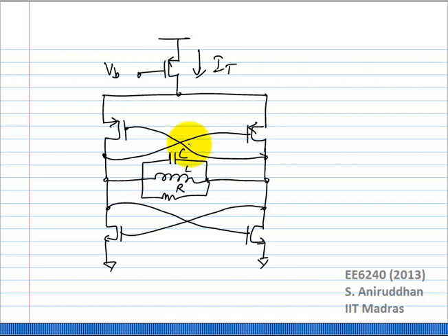Okay, so let us take the first example. So he said that for the same current I get twice the negative resistance. Correct? So let us say this was GMN, and I make sure that GMP equals GMN. Suppose I had taken the original NMOS cross-coupled oscillator and just made the width 4 times for the same current. Would I still have got twice the GM?